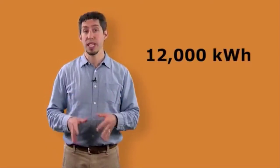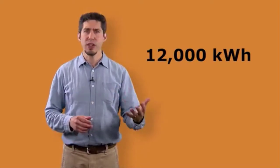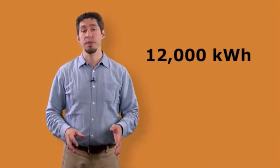Let's consider this example of an annual usage of 12,000 kilowatt hours, an energy demand that's a little higher than the average United States customer. One way to look at energy demand and photovoltaic system design is to plan on replacing 100% of our energy from a traditional utility with solar. So if we use and pay for 12,000 kilowatt hours per year from our utility, then we would want to produce 12,000 kilowatt hours of electricity from the PV system during the year so we come out even. Now that's 100% of our annual demand.